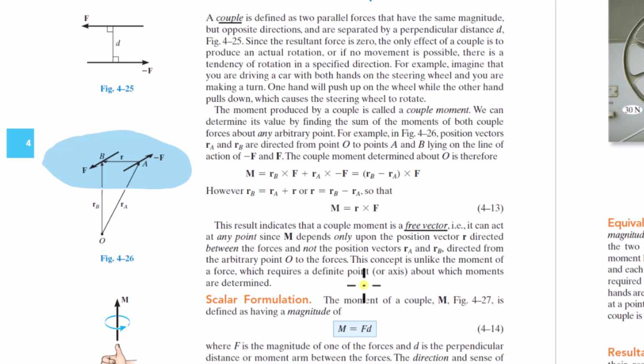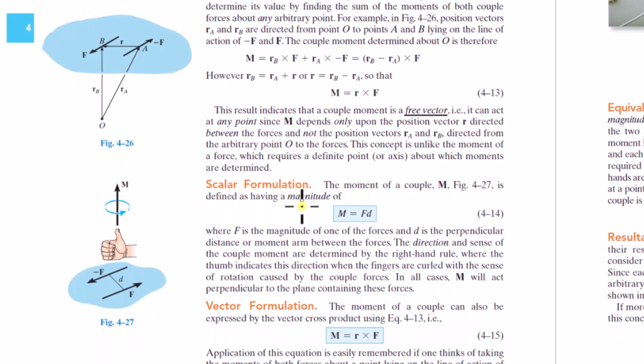It's going to be important to understand sliding vectors, free vectors, and fixed vectors later in this chapter, if we want to rearrange force systems and mold force systems in different ways. And the vast majority, if not all, force vectors on bodies are sliding vectors, not just in the context of calculating moments. For all circumstances, you can slide a force vector and it won't change the result of any statics problem.